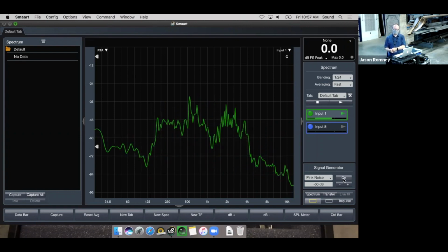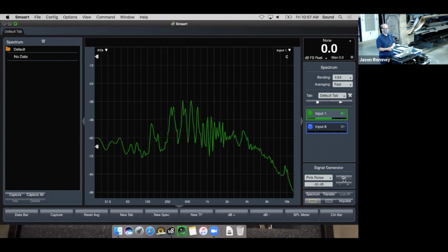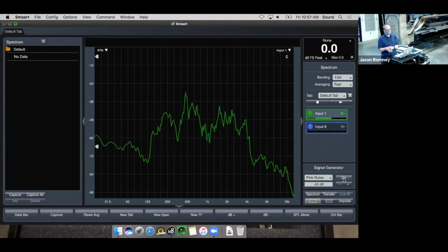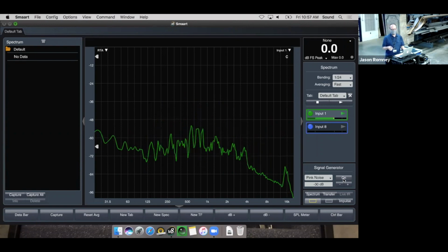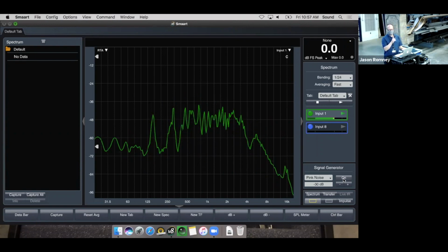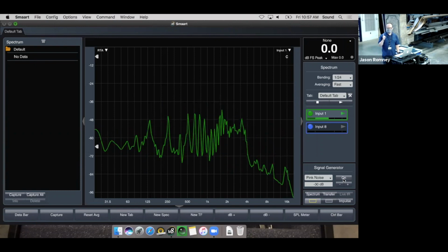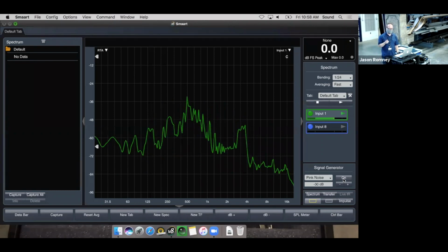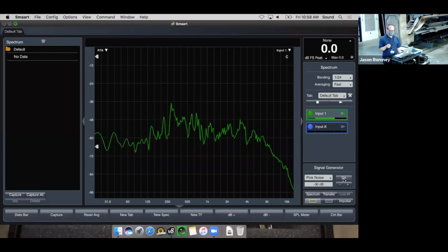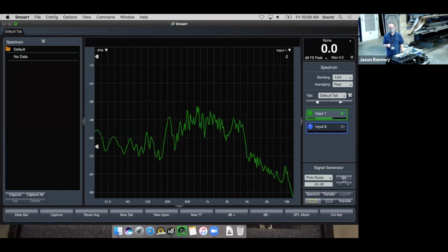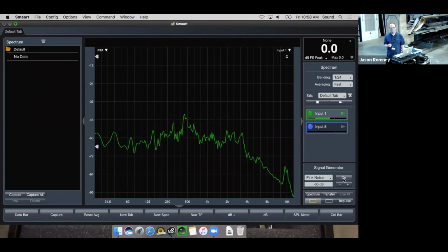The only thing I've ever seen anybody use this for that is even remotely useful is that when you get a feedback frequency, you will see that sine wave spike on this spectrum view. That can be really helpful for people who like to use EQ to solve their feedback problems, which, as I taught you last year, is the worst way to solve your feedback problems.